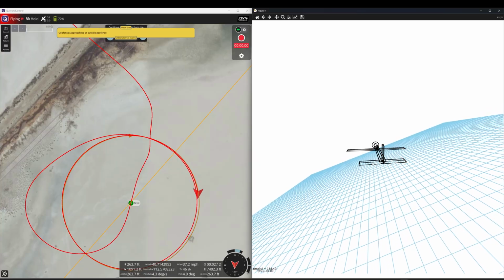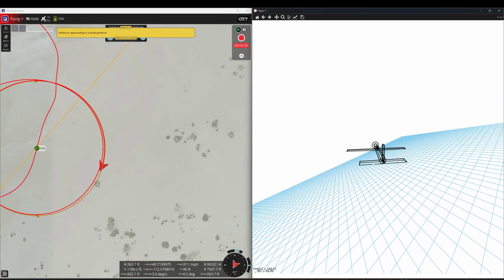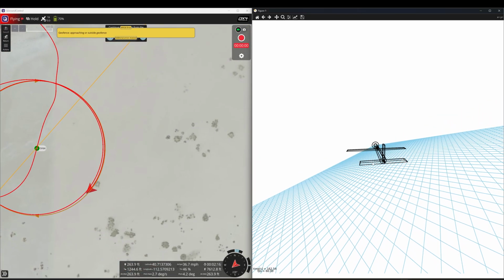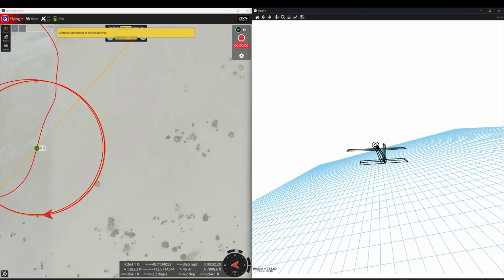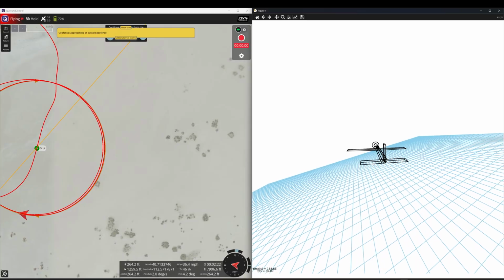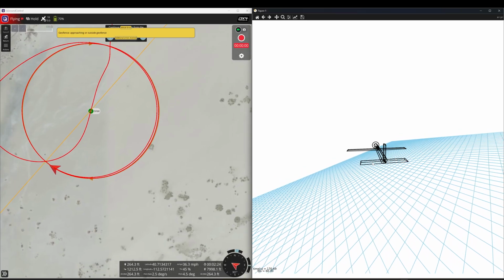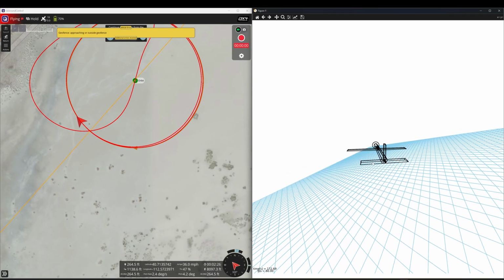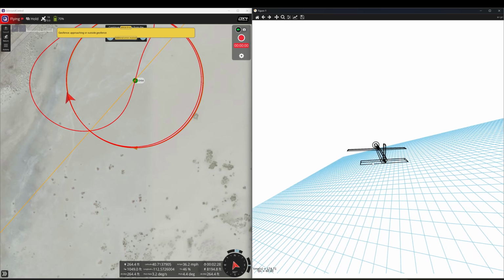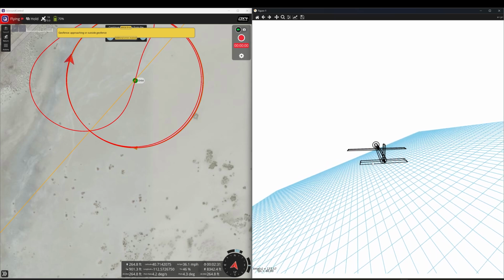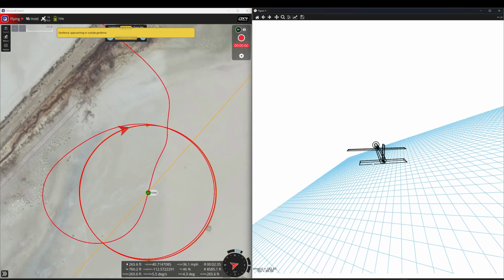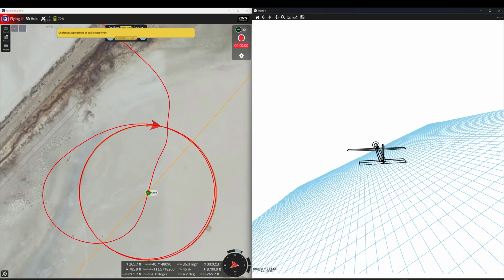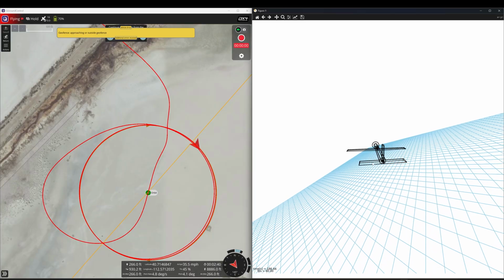So you saw that we had no information about the aerodynamics of the vehicle, just basically geometry, sizing. And so within minutes, we were able to create a vehicle that we can actually fly around and that we could use to develop control laws and test other aspects of the vehicle without investing a lot of time and effort into CFD and wind tunnel. But once we have that, we can actually replace our vehicle model with those higher fidelity models.